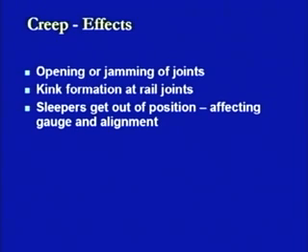It will also create a problem to the alignment. So, both are quite difficult conditions. They are going to affect the total operation of the trains and the safety of the movement of the trains on that section. So, we have to take this into consideration. If there is a heavy creep and there is such movement of all the components, then that needs to be rectified.